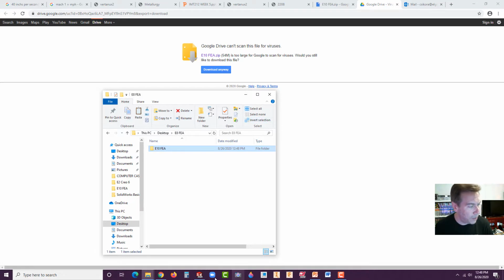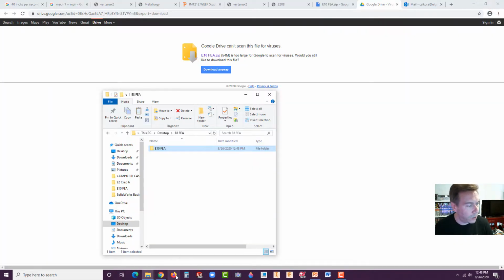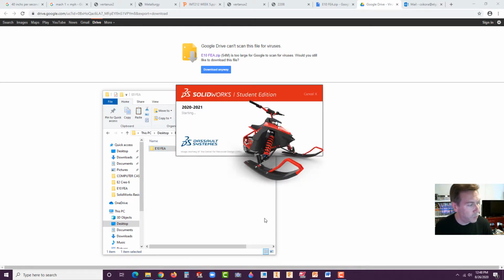All right, now I'm going to restart SolidWorks here because I have that old data in there and I just want to start fresh. You'll find sometimes, this is a little side note, if you're working on the same part and you want to modify it and the original parts are in there, it's sometimes best to close out and restart, so it doesn't pick up on the old models and the changes you made in the event that you want to discard those changes.